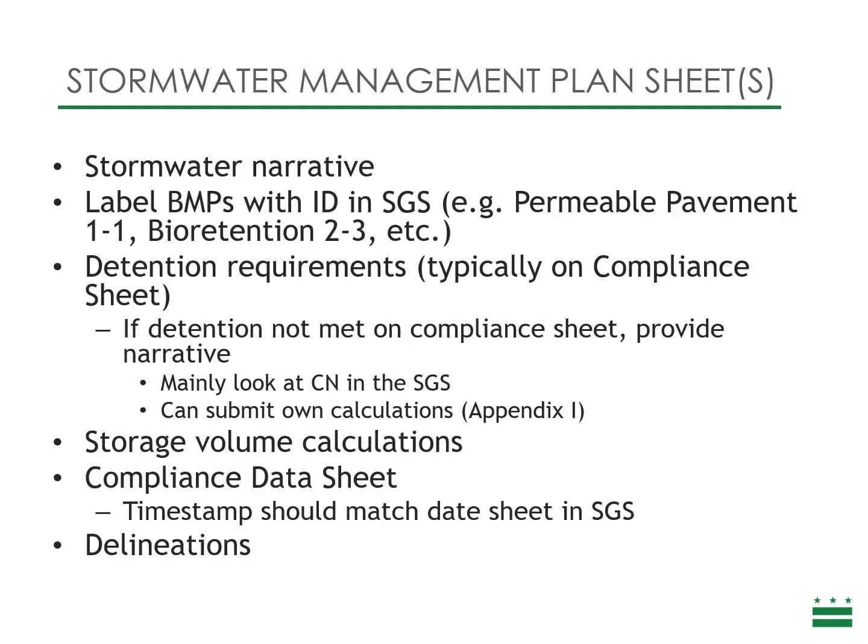So to summarize what should be on stormwater management sheets, there should be a stormwater narrative, label the BMPs with the ID given in the SGS, show that detention requirements are achieved. That's typically shown on the compliance data sheet, but if it's not met on the compliance data sheet, you should provide a narrative. You should show the storage volume calculations, the compliance data sheets with the timestamp, and delineations of contributing drainage area and site drainage area.